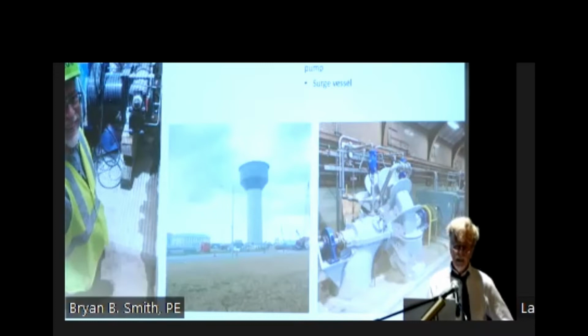Now, if you're designing a system working in a chemical plant, this is a good starting point for analyzing a system from a pressure surge, transient, water hammer, whatever you'd like to call it. With regard to engineering design, it's been pretty much open. There's no standards committee up until last year when it comes to computer surge modeling and design. With the Hydraulic Institute, we started a pressure surge committee this year to address standards, operation design, software, and more details in the system.